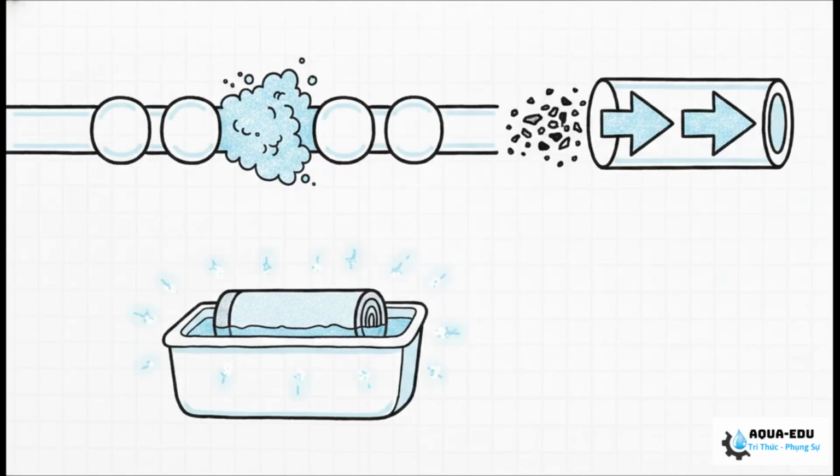Now, I want to pass down a couple of veteran tricks I've hammered into my crews over the decades. When you're cleaning a multi-stage system, clean it one stage at a time, period. This focuses all your pump energy and keeps your flow velocities high enough to aggressively blast those foulants out of the spacers. Also, always make sure your cleaning flow matches the normal feed flow direction. If you try to reverse it, you can cause telescoping and permanently destroy the element.